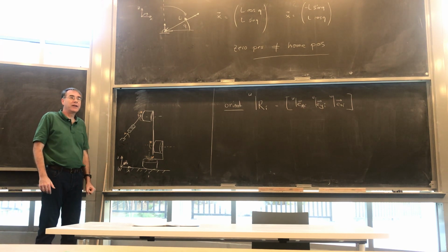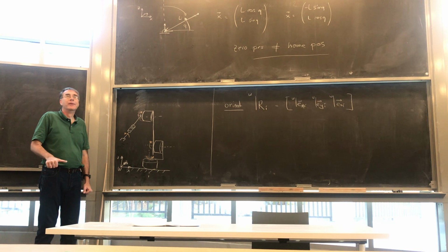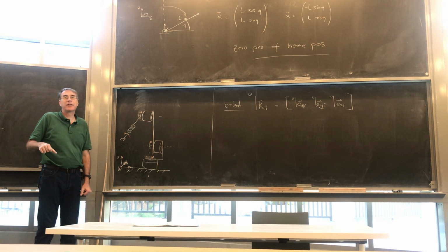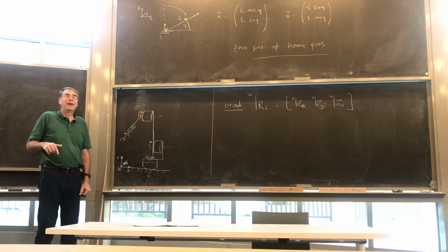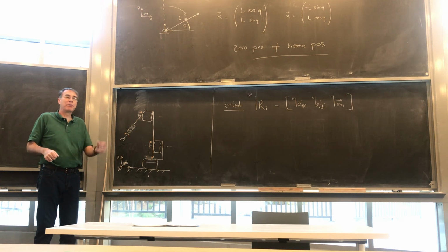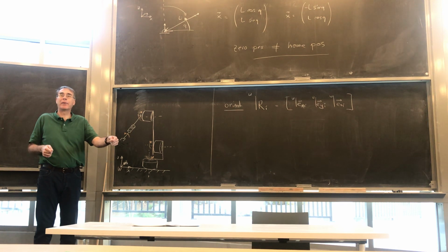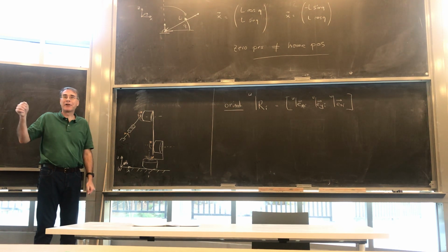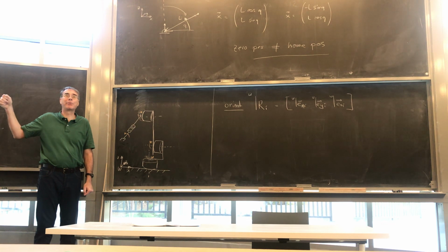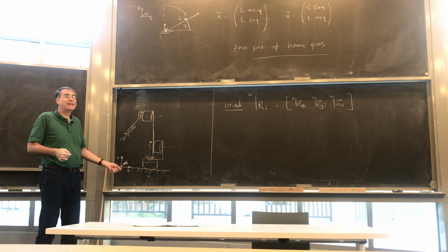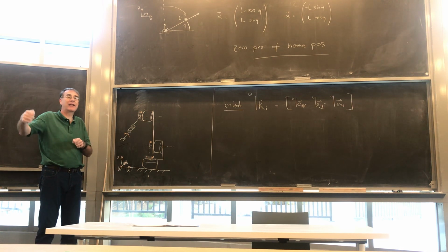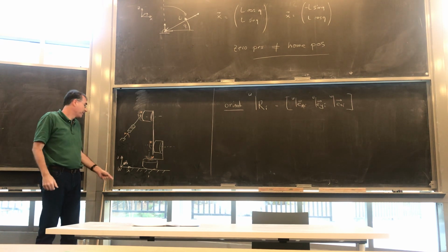So basically, put a point on your table. Put a dot on it, and actually literally put a dot on it. If you don't mind, put a piece of tape on it and then put a dot on it so that we can erase it more easily. At some point, you're going to put a block down or an object, and you're going to take out a ruler and say it is 30 centimeters from my origin, right? And then your algorithm better come up with 0.3 on the display to localize it. These are physical things we're now measuring. So place a real reference frame that you literally take the ruler relative to and measure the distance from. That's my world frame.